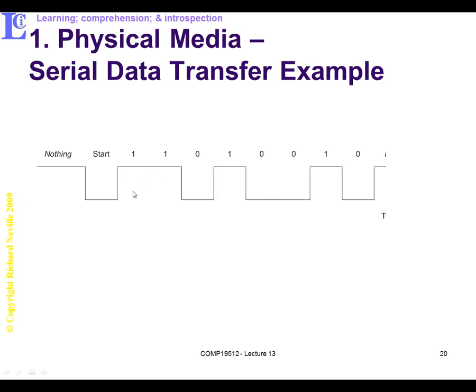The reason I'm making this happen again and again is to physically show you how a single bit is sent one after the other, sequentially. And as you can see, this is serial transmission. Now when it finishes, it goes back to the nominal state and the receiver knows, okay, I've picked up 1, 2, 3, 4, 5, 6, 7, 8. I've picked up a byte. It might be serial, but it's picked up a block of data after being told here that the start of transmission is occurring.